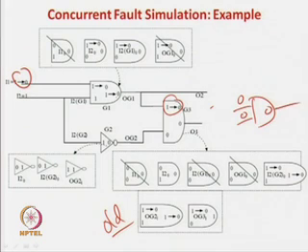Okay. So now you see that I1 is stuck at 0. This stuck at 0 means it is 0 0 and 0. So this gate exactly becomes similar to the normal case of this one, so you can delete it. Now I2 stuck at 0. So this net is stuck at 0, if you think, so this one will become 0, this one will become 1. So this is a 1, okay, and these two are the same as in the previous computation. So this gate is retained.